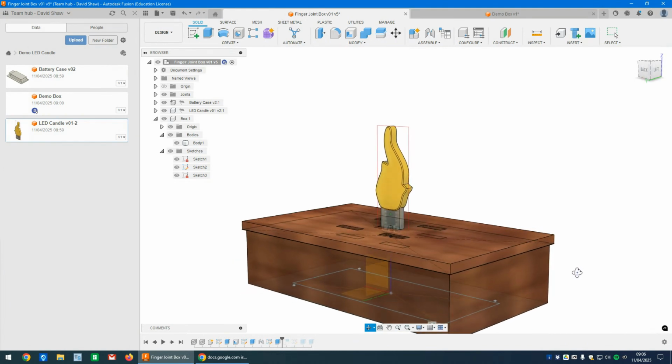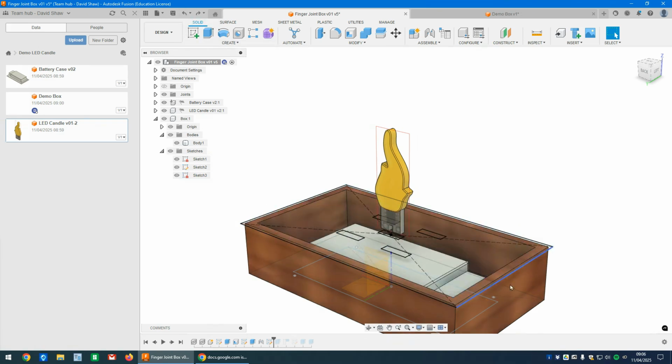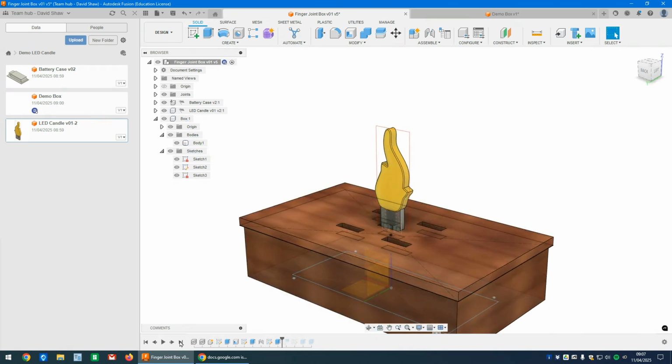And just to point out here as well that when I make this box, my intention is not to have any finger joints coming into the lid here. I want this lid to be nice and clean. So just to be clear, finger joints to make all the rest of the box, but here I'm going to have basically glue on the top face here, and then I'm going to just glue straight onto that this top box for a nice clean finish.